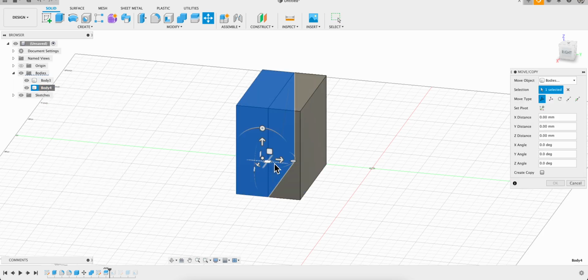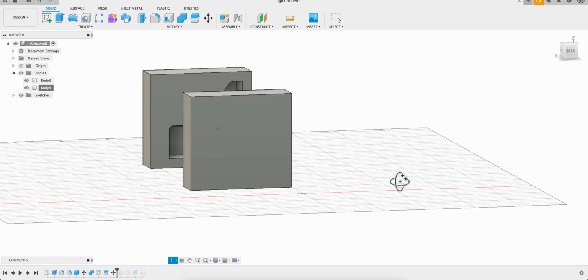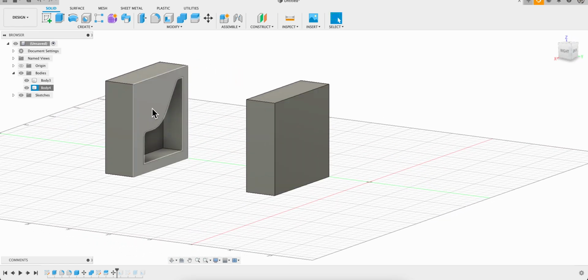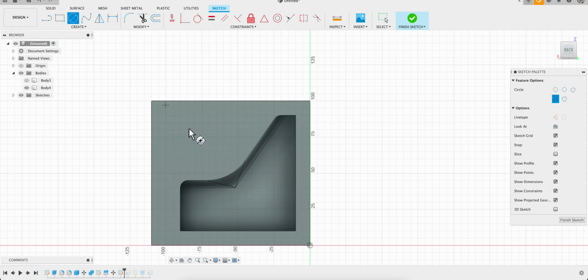Okay, so I move out one of the bodies, so I can pour the plastic in and then hold it in place. But before I hold it in place, I need to draw items to clip it on. So you can create anything, like I will use a rock shape, maybe around 20 mm. So this one will be the male. So the male, as I told you, you need to have 0.2 mm of difference. So the female will be 20 mm. So the male will be 19.8.